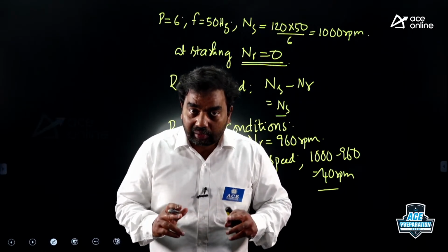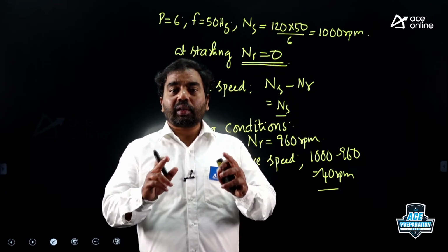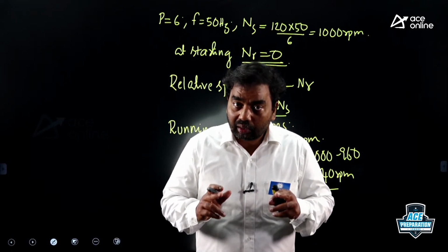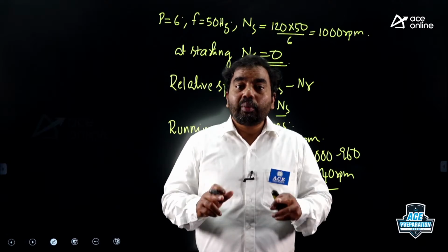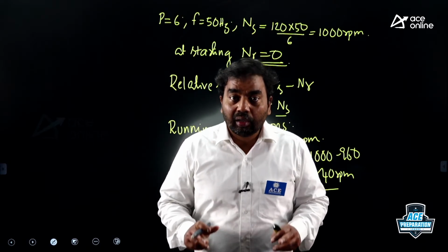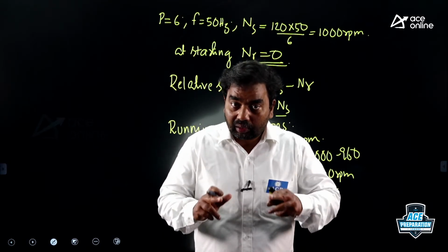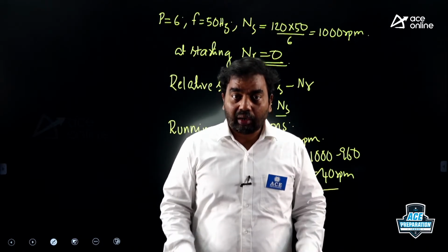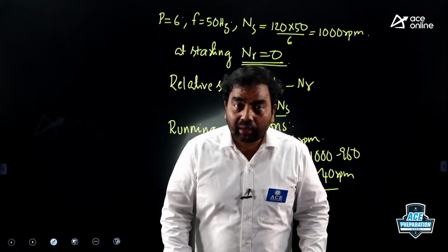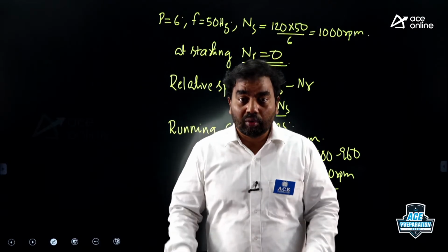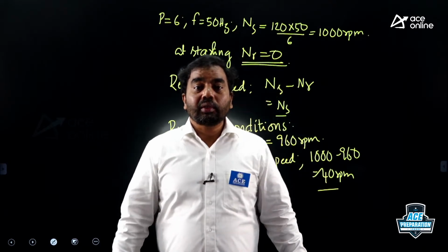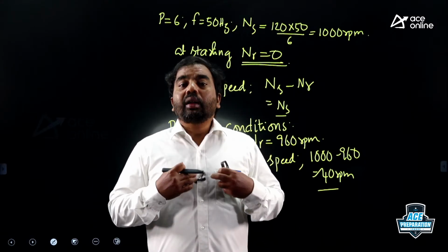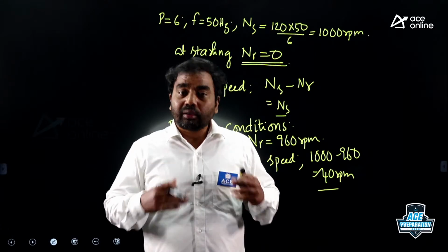So finally, can I say like this, the purpose of starters for a 3-phase induction motor is not for starting a motor but to limit the high starting current. So the main purpose of starters for a 3-phase induction motor is to limit the high starting current. Magnitude wise, these starting currents will be 5 to 8 times the full load current. If such high current flows in the motor winding, what happens to the windings? Damage.